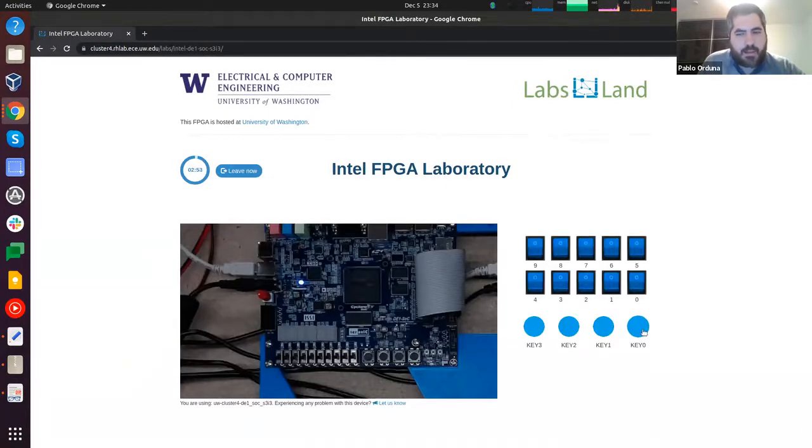When I click on this button, it's not a 0, it's something else, like a reversed 6, and the reason is that I changed one of the LEDs in the 7-segment display, turning it from 1 to 0, and the one in the middle from 0 to 1. Everything else will work in the same way, but given that I only changed that particular code, that's the only change we see here. Everything else, the LEDs and so on, is working.